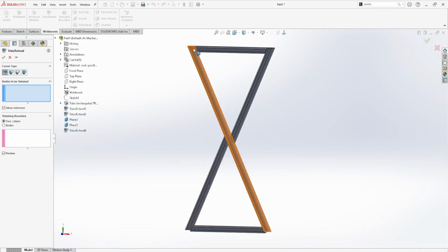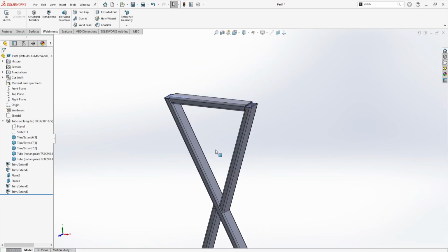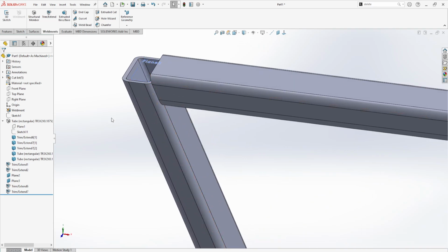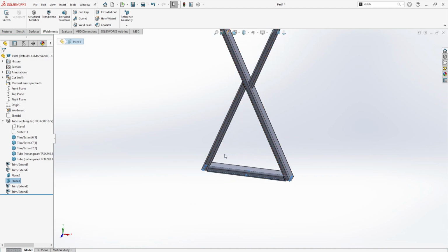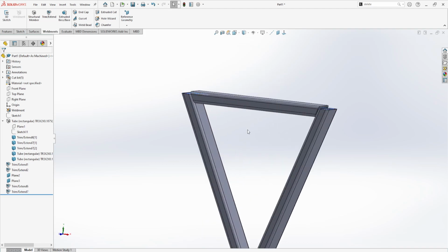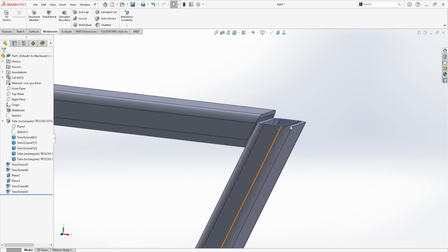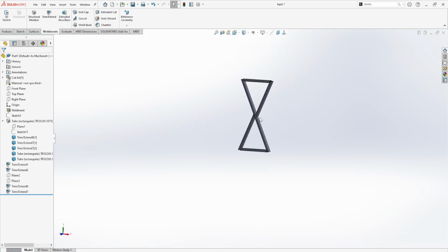and then you can trim extend. This body and this body needs to be trimmed on the top plane. So you can click the top plane. Now you have only 2 items in your tree. So it's always good to look at whether you should do your trim extend per body or per cutting surface to get the minimum amount of clutter in your tree as possible. But that looks good. So now we have room for our end caps, so we can go ahead and hide these planes. Now we will be ready for the next step.